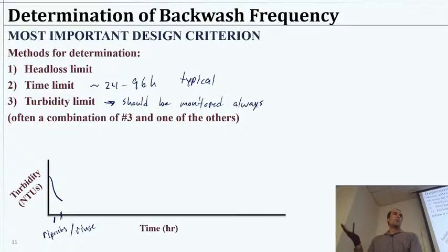So essentially how long we rinse is about how long it takes before we have a low level of turbidity that's pretty much stable. So then we're going to do operation or filtration for some time. For the next many hours, this is what we want to be a big number. We're just simply going to be doing filtration, or maybe we'll call it production. We're producing water up until we reach a spot where we can no longer filter.